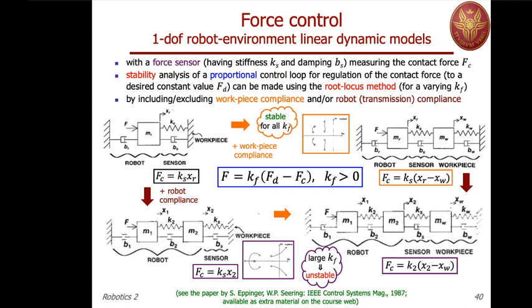Of course, you can imagine other forms of force control. You can introduce a feed-forward term of the desired force. You can introduce an integral term, and so on. And things may change, but you can still do a linear analysis that predicts stability or instability in the closed loop for this force control.